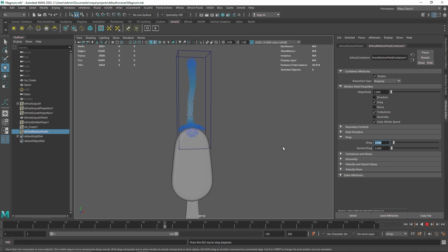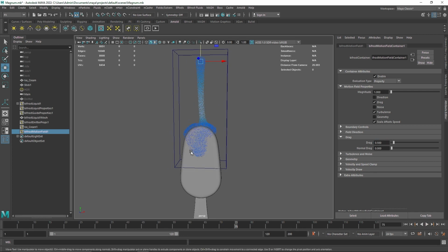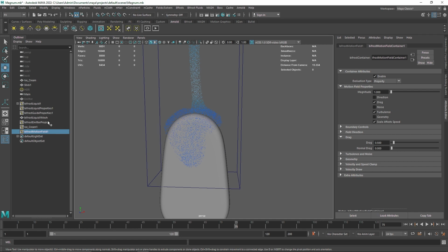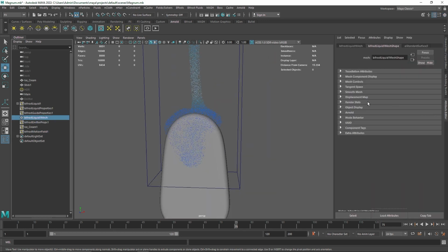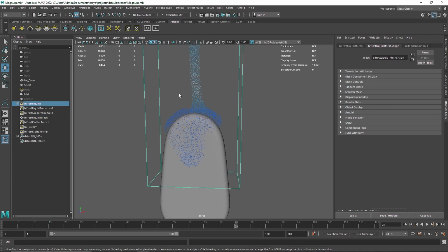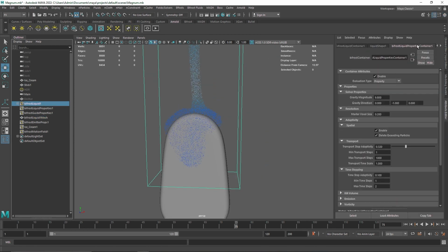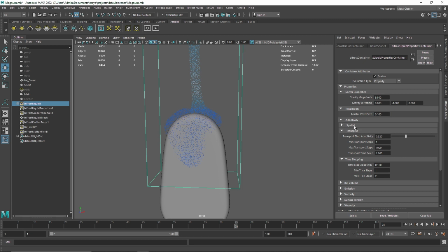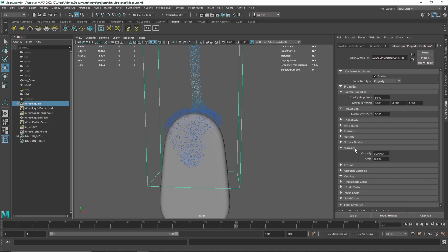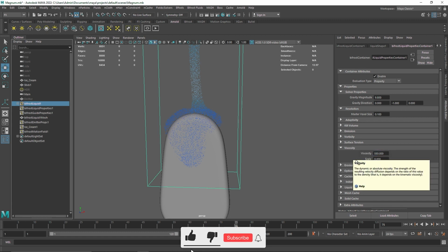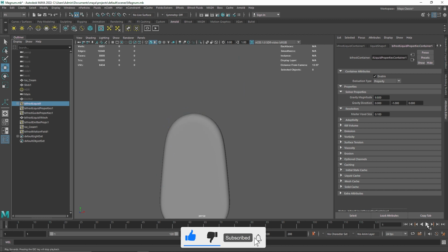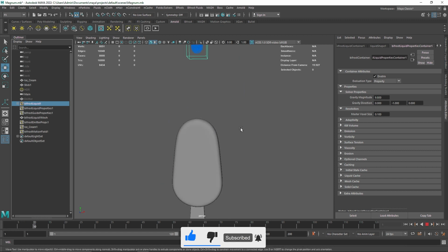Let's keep the drag on and let's pour the overall liquid here. And it looks pretty good. I think the one last thing we need in this is a bit more viscosity. It's not properly dripping out that much. So what I'm going to do is go to the liquid and change this here. And again, I'm going to go to 0.100 just to see my final sim, how this is looking. Let's turn everything off. Let's go to viscosity and maybe a 550 value. And that's it. So let's go back and we'll go for a final scene and then we'll maybe shade it.